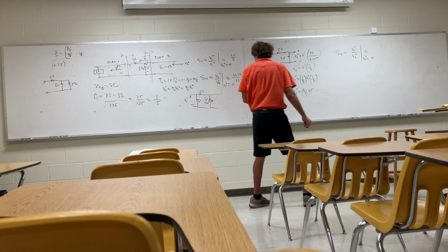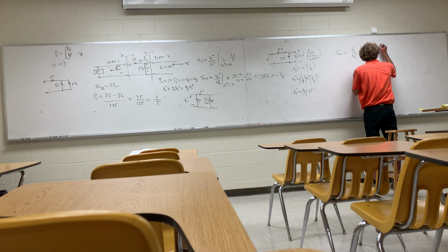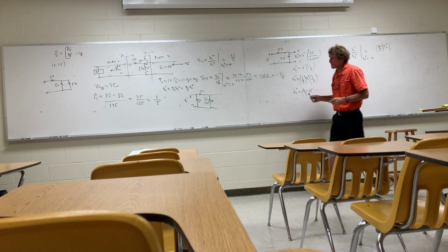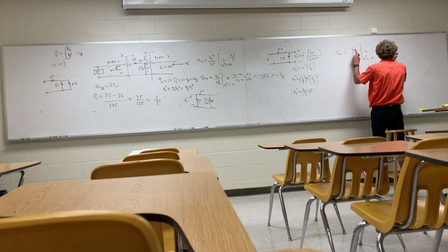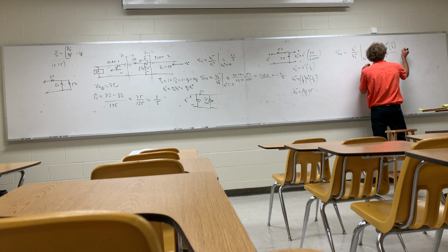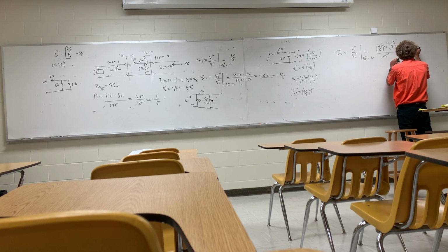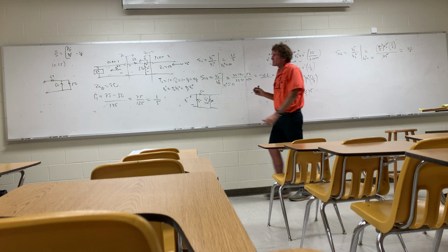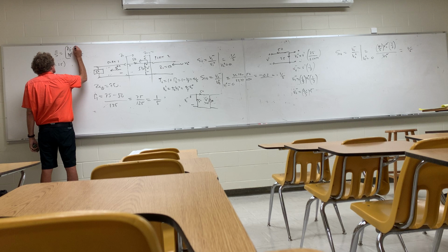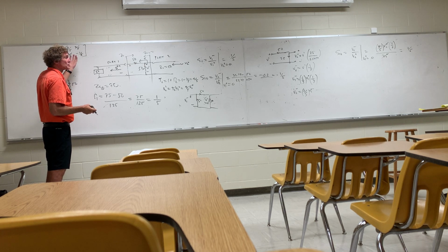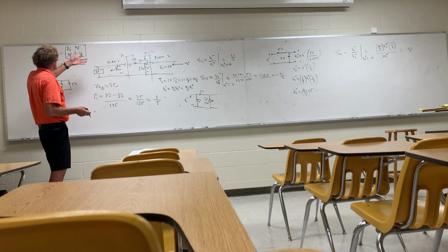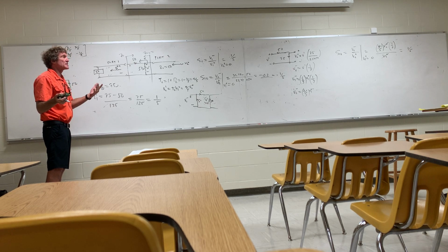So I have 4/5 V2 plus, times 1/2, and that would be V1 minus divided by V2 plus. The V2 plus cancels, and that means my value there is simply 2/5. So now the S parameters look like this. This is 2/5. And to see if it's a reciprocal network, if I take that times its transpose, it doesn't give me the unitary. It's definitely not lossless. But just because it's asymmetric, you can tell it's not a symmetric, not a reciprocal network.